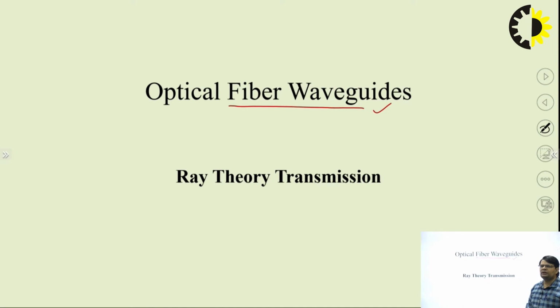Now to explain the propagation of light inside the optical fiber cable, the ray theory of transmission is used. There are two popular theories, ray theory and wave theory. Here we are discussing the ray theory part only. In the ray theory, light is considered as a ray, and this theory is applicable only when the dimensions or size of the optical fiber cable are sufficiently large. And as compared to the wave theory, this ray theory of transmission is not as accurate.